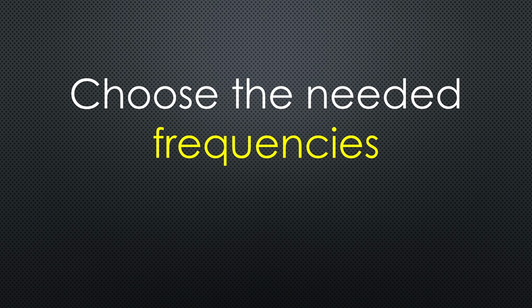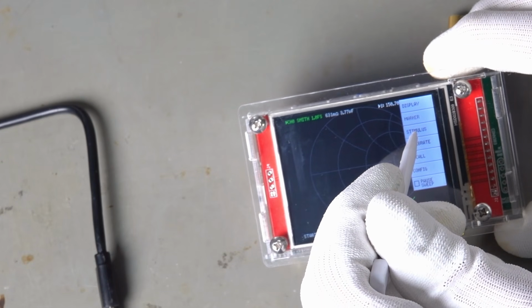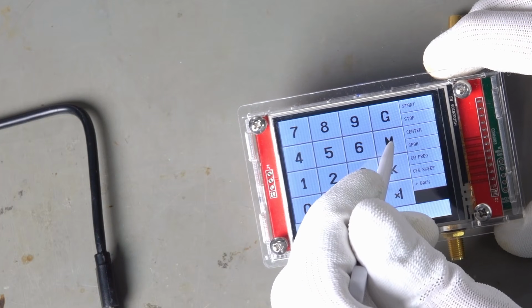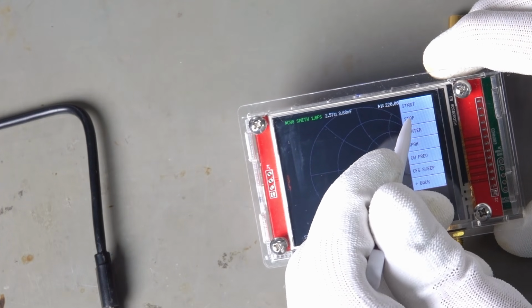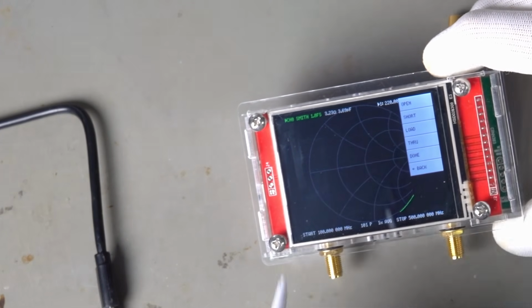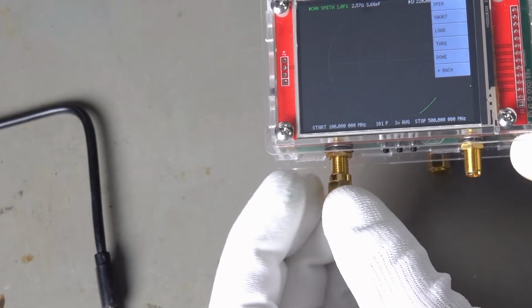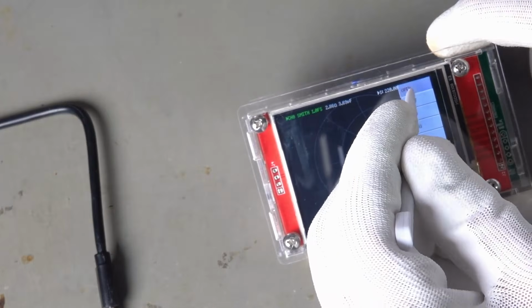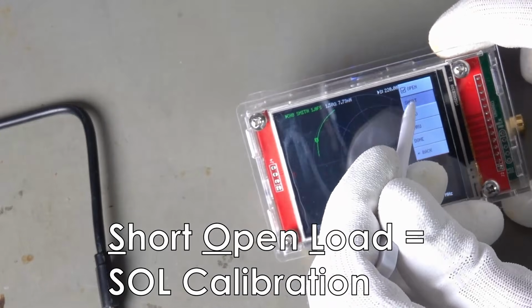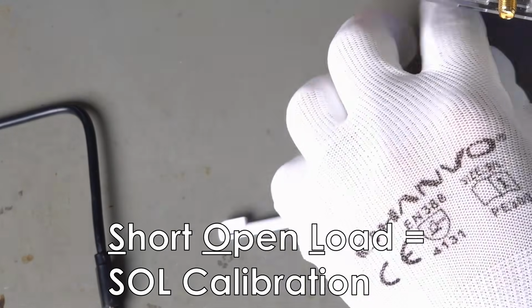The calibration process is relatively easy. First, choose the frequency range you want for your calibration. This is very important because the NanoVNA invalidates a calibration as soon as you change the range. Then we go to the calibration menu and start with connecting the short to the VNA. After waiting for a short time, we can go on with the open and the load.